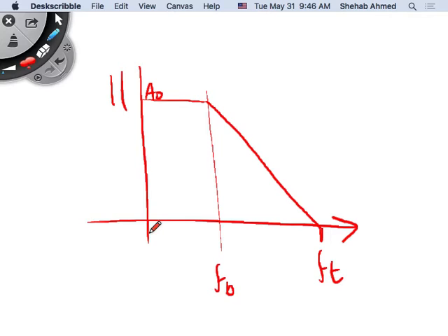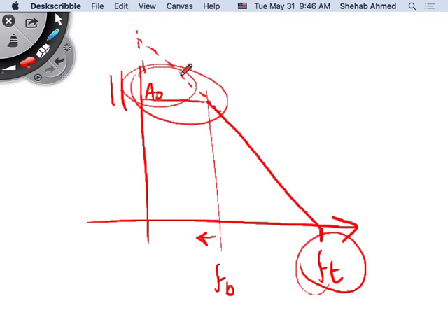So they're telling you that the most consistent parameter is FT. And you can sort of approximate the others by knowledge of FT. Because we know that FB is low and A0 is high. So at some point in this region here, we have an FB and we have an A. Is the value of gain going to be very precise?